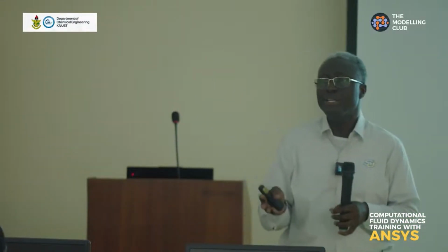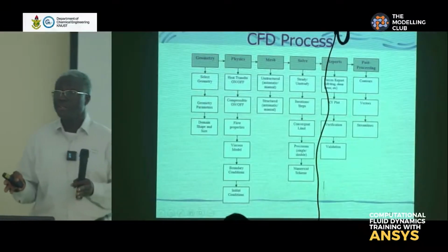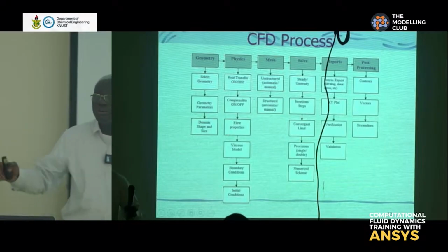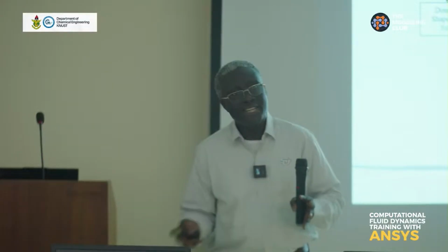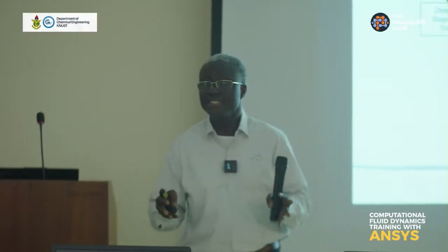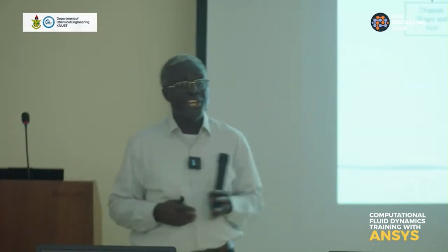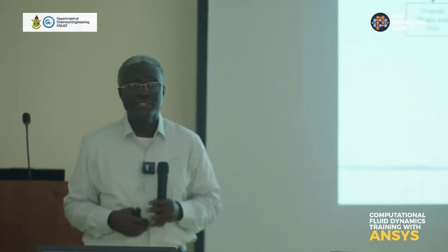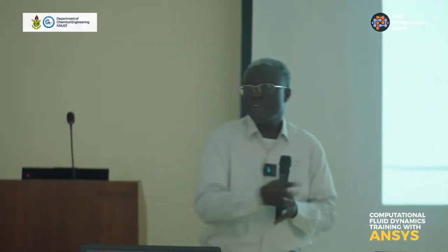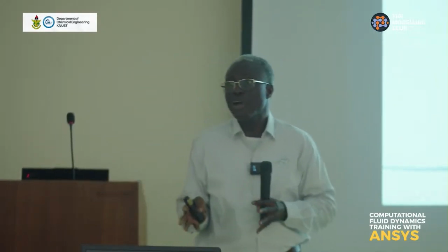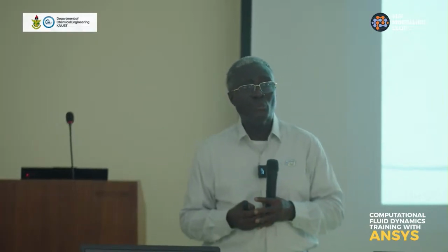Another case in point is, properties are temperature dependent. Let's solve the problem for constant temperature and get a baseline. And then let's throw in more complexities to see how your system will change if the temperature changes when you include the nonlinearities. Or let's first solve the simple laminar flow problem before we make it more complicated with turbulent flow.